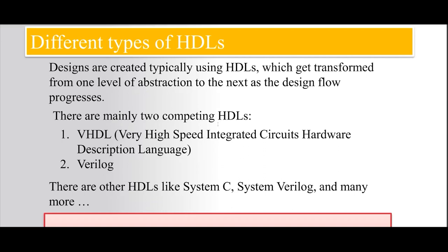Whereas C language, C++ or Java cannot be used to design the hardware because those syntaxes do not allow us to describe these things. If you want to store any data, we need to use a register, and for a sequential logic circuit we need to generate the clock. These are all things involved in hardware modeling. That's why the Verilog language is preferred to describe all of these things.